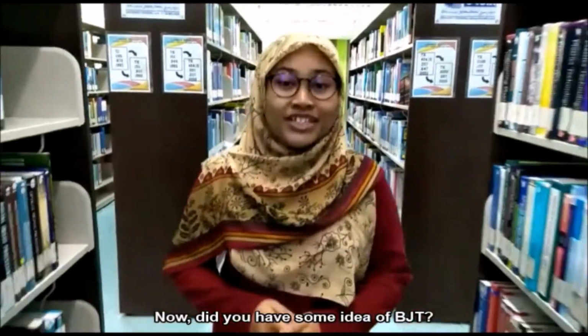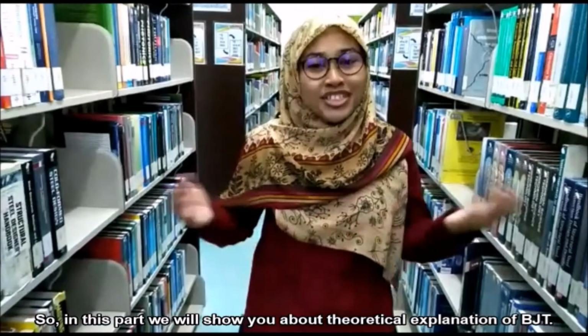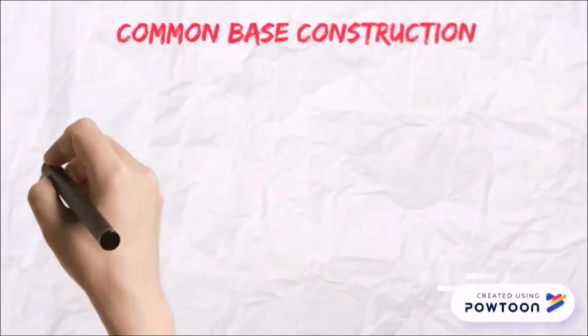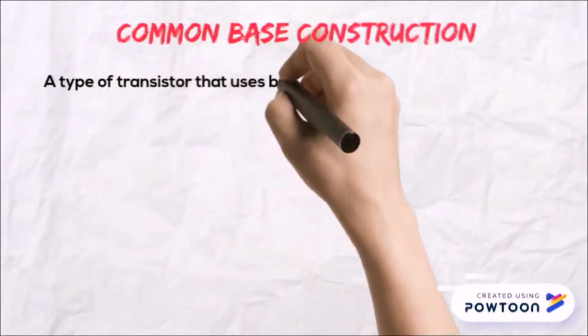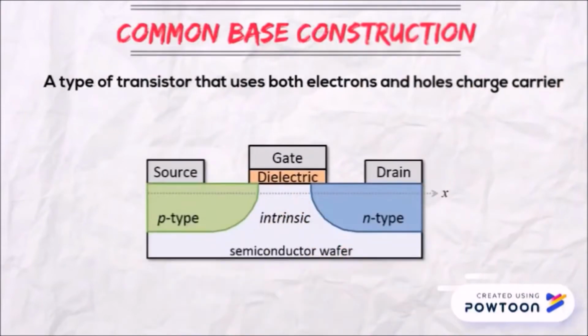Now, do you have some idea of BJT? So, in this part, we will show you the theoretical explanation of BJT. A BJT is a type of transistor that uses both electrons and holes as charge carriers. A BJT consists of three layers of doped extrinsic semiconductor material sandwiched together. Each layer provides a wire connection to a circuit.